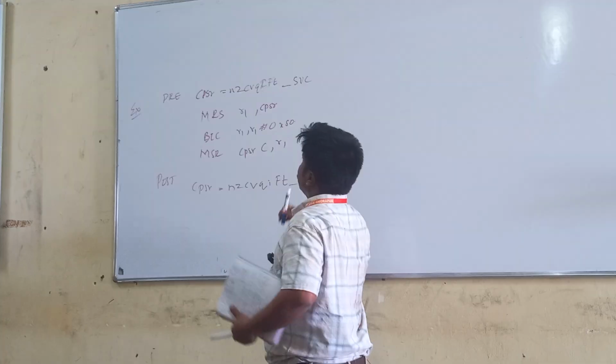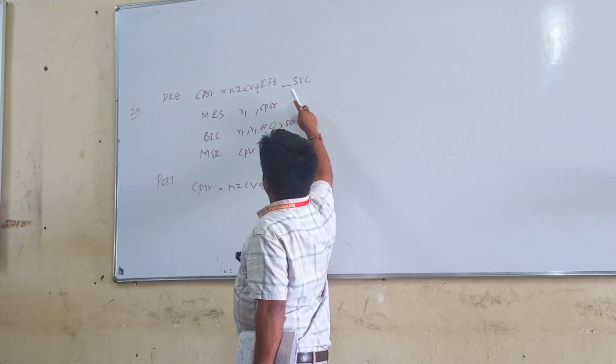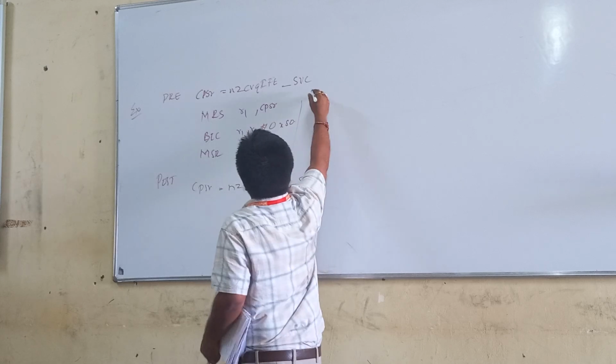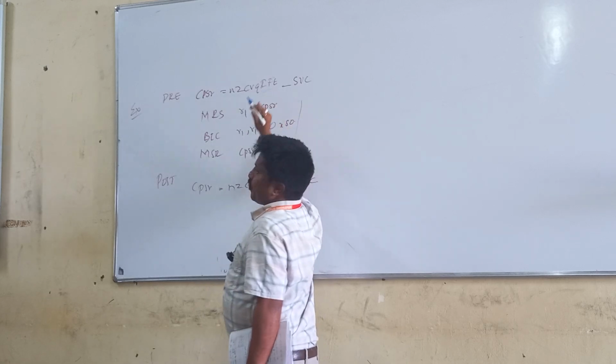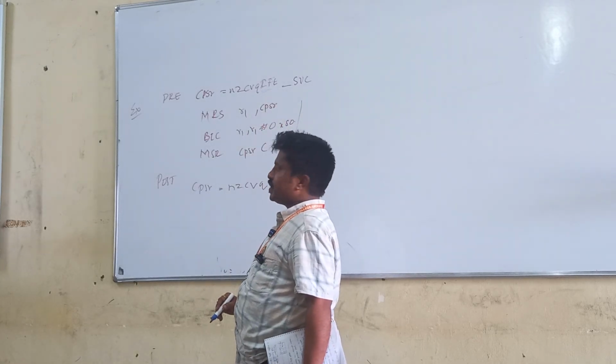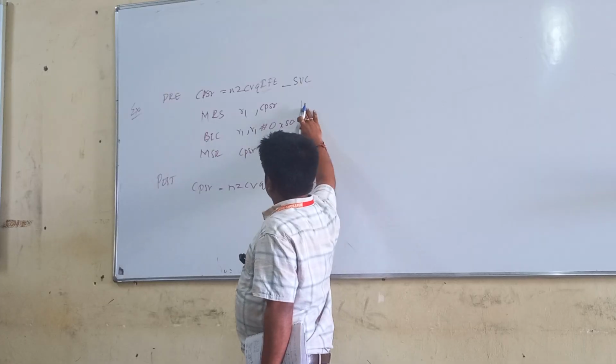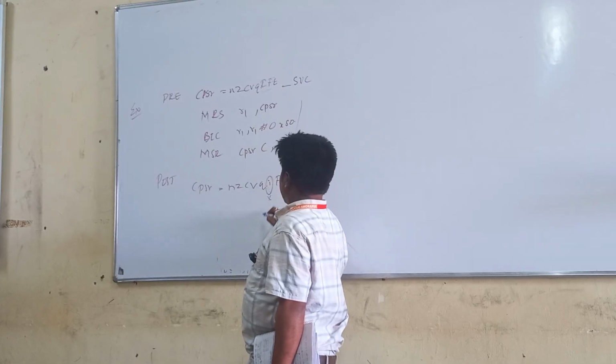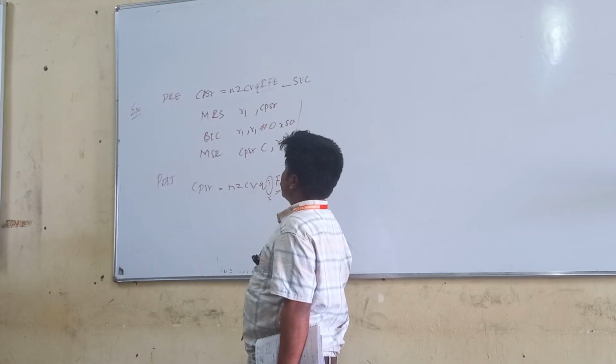This is the precondition before executing these instructions. We have the CPSR with the interrupt and the fast interrupt flags raised here. But after the execution of these instructions, the interrupt flag will not be raised, only the fast interrupt flag is raised here.